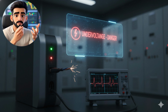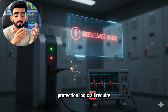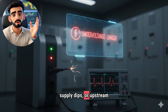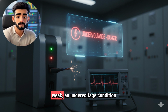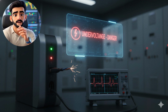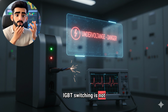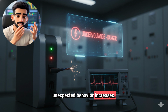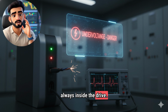DC bus level, because its control circuits, gate drive circuits, and protection logic all require a stable supply. If the input AC supply dips, or upstream breaker contacts are loose, or cable joints are weak, an undervoltage condition can occur at the VSD input. In this condition, the drive will trip because IGBT switching is not stable at low voltage, and the risk of unexpected behavior increases. The root cause of this fault is not always inside the drive.